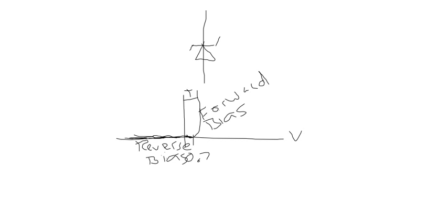Now, if we go far enough in the negative direction, we hit another break point that we call the breakdown of the diode. And it doesn't destroy the diode. Going into breakdown really doesn't hurt it as long as you don't put too much current. If you put enough current into it, in either direction, you can burn a diode up. But if we go into that breakdown region, we're really locking the voltage in at whatever this breakdown voltage is.